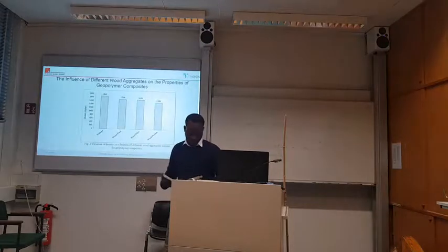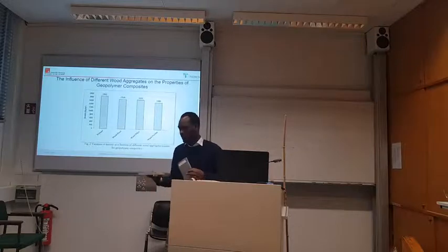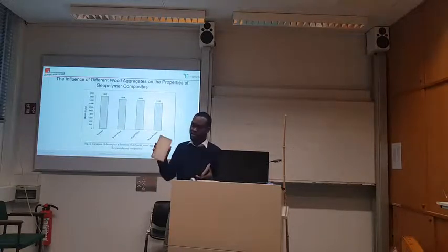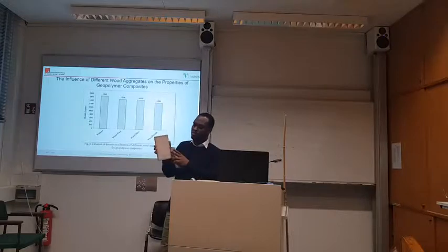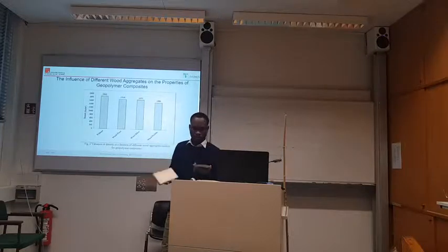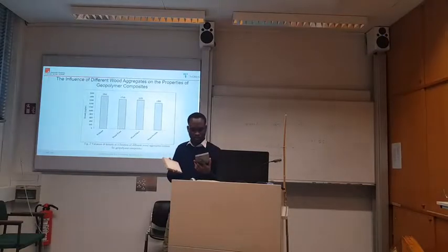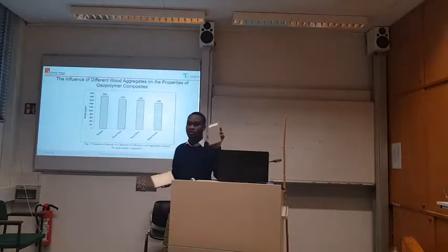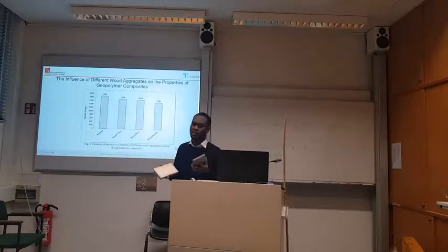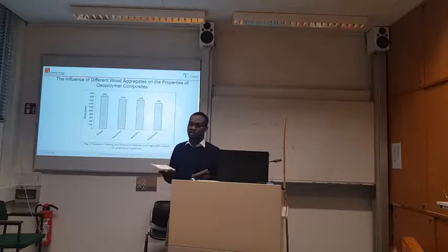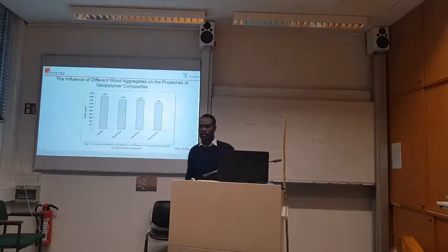And also the color, you can see, we didn't apply any color. Metakaolin is mostly a bit whitish in the beginning, but with time the water was coming out and we didn't store them under the right conditions, so the color begins to change on the edges. Fly ash is mostly grey, so this is the original color of the product. Metakaolin is much lighter, but occupies much more volume and needs much more water during the mixing, but this one needs less.